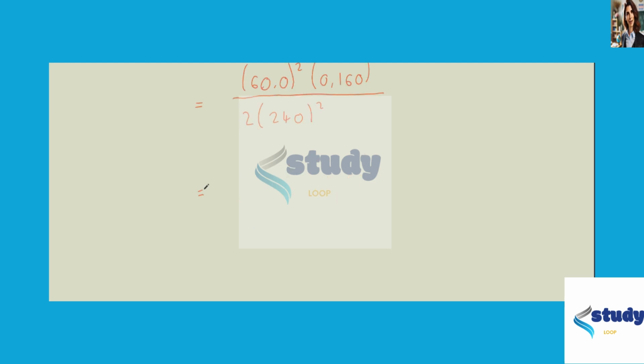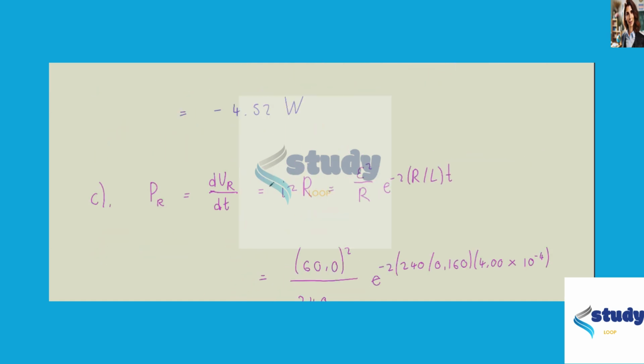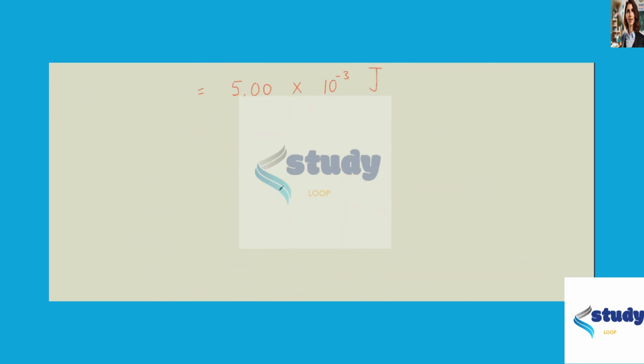And hence we get the total energy dissipated through the resistor after a very long time is 5 times 10 to the minus 3 joules, which is the same as the answer in part A. So what this means is that during the decay of the current, all the electrical energy that is originally stored in the inductor is dissipated into the resistor.